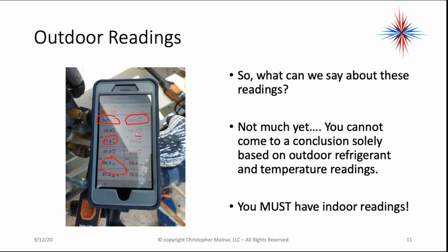But what can we actually say about this? Is it right or wrong at this point? Not really. You can't say anything just based on the outdoor readings. You have to have indoor readings, because a technician here could say this system is overcharged and not realize exactly what's going on. Remember, I have an 8-story line set here as well. It's very important to remember. This is not a short line set. This is a very long line set.